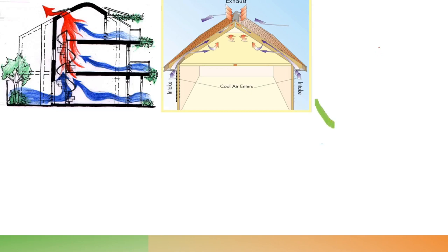If you've got a standard roof, and you look up under what's called the eaves of the roof and the soffit, you'll see ventilation, little slots, or you should see slots there. Older buildings not necessarily, but certain new builds, you will see vents all the way along underneath the sides of your roof, and then there's also a vent in the top of the roof.